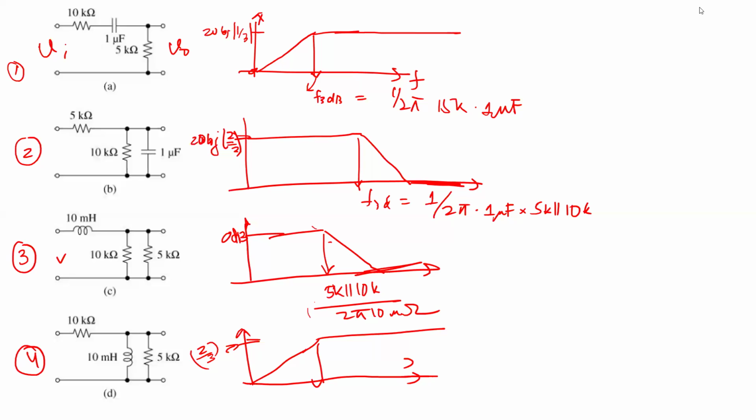Whereas in board design, because the loop sizes are large, you get sizable inductors. With just a PCB trace, like a circular trace, you can easily get maybe not microhenries, but a couple of 100 nanohenries.